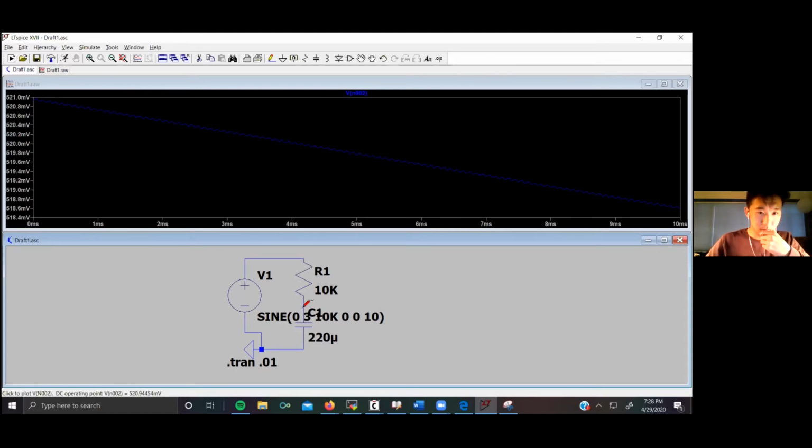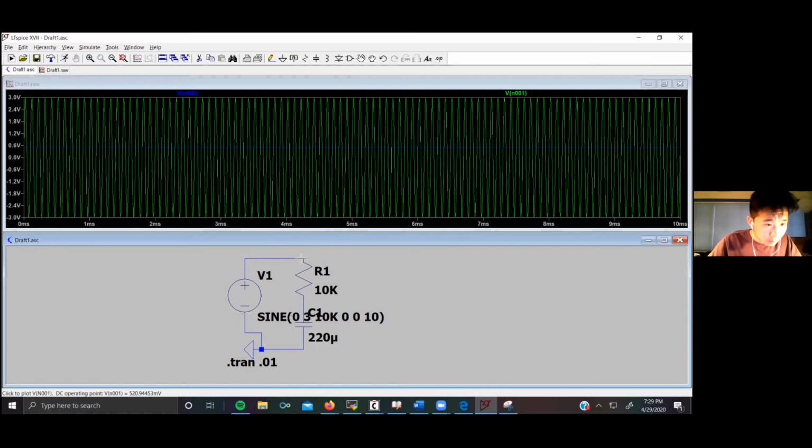Yeah, you click between the resistor and the capacitor, right? So this is the voltage across the capacitor because it'll take this voltage at basically this node and compare it to your ground voltage. So this is actually still technically rather similar to the voltage on here. So you can see like, okay, this is 0.6 volts versus this is 3 volts, but it's rather DC. We can actually change that by increasing the frequency.